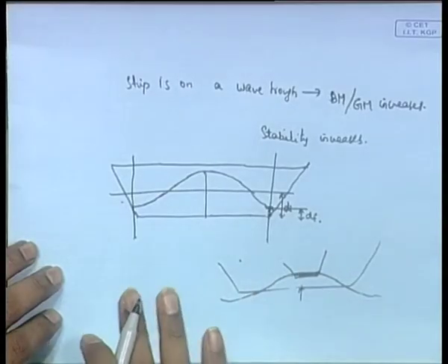At any point, that means between any two stations, that small strip, the moment of inertia is proportional to B cube, or the half breadth cubed. Therefore, what we see is a very strong decrease in draft in the front part of the ship and in the aft part of the ship as a result of the ship floating on a wave crest, as a result of which there is a very sharp decrease in the effective half breadth of the ship.